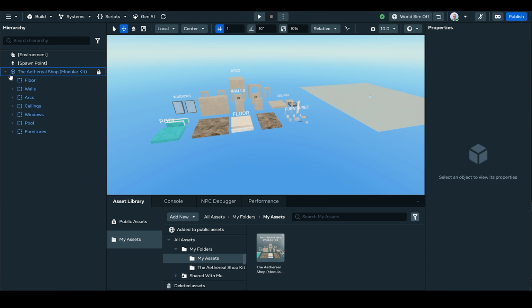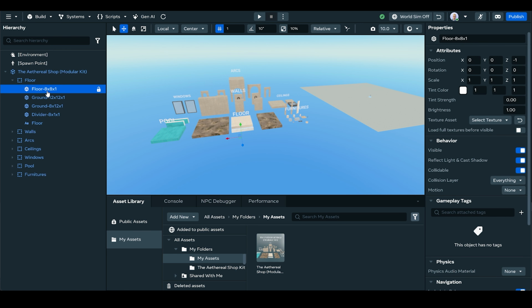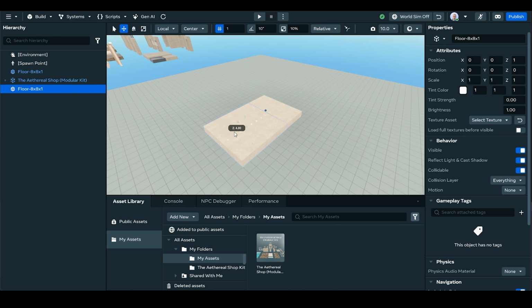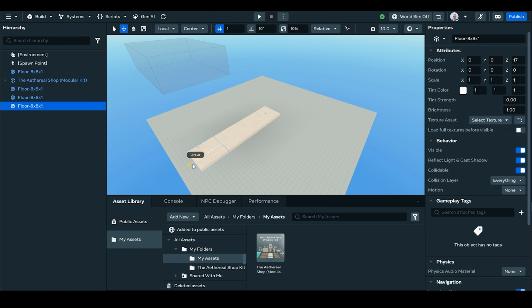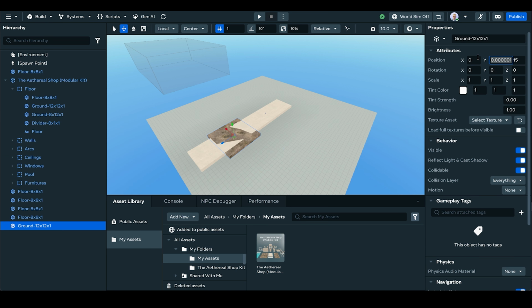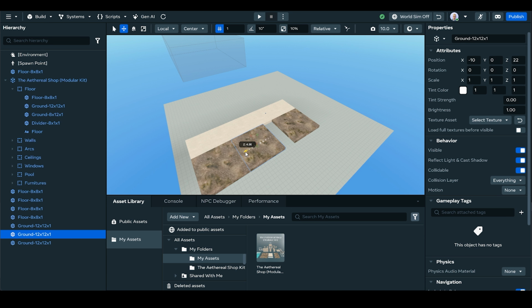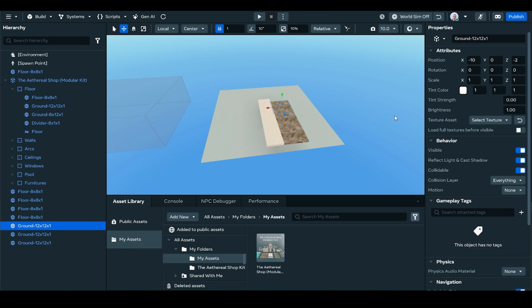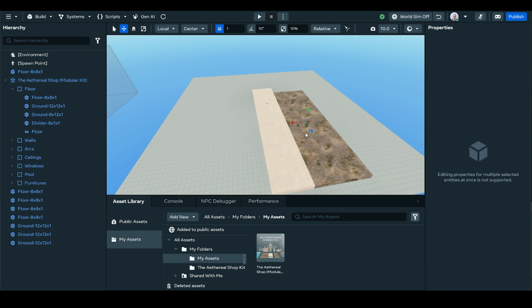It's recommended to enable grid snapping when using the Move tool, so your objects will align precisely in place. Once you've chosen the piece of the kit you want to work with, make sure to duplicate it first. Then, ungroup it from the main kit and remove it from its parent. After that, reset its position by setting the X, Y, and Z coordinates to 0. Now you can freely duplicate that piece and repeat the same process for every other object you want to use from the kit.